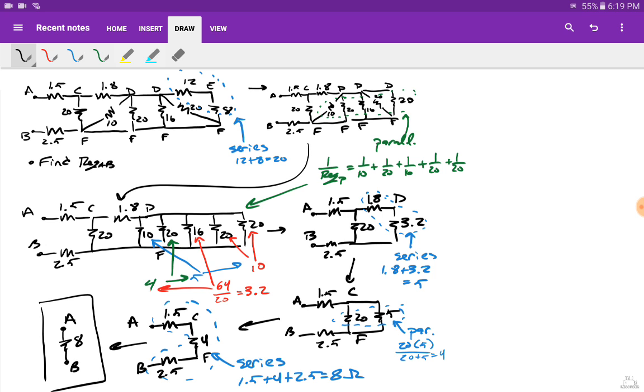Don't look with your eyes, all right? Pay more attention to what's sitting between what two nodes, all right? And if I were to generate a current, if the current were to ever break, use those ideas to identify series and parallel. Not, oh, those are right next to each other, so those are in series. No, that is not how it works, okay?